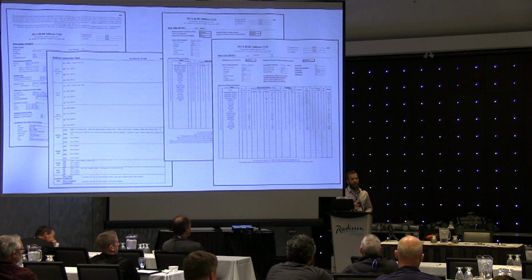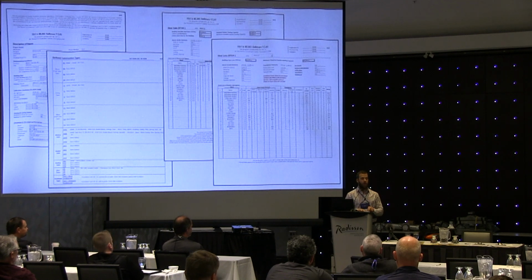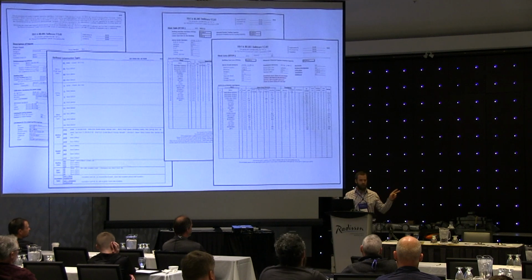Yes, in a way. All the building details, the location, what the walls and windows and everything are made out of, R values, you can confirm really quickly, like you said. However, the dimensions of each element, we don't duplicate on the results. So maybe I have an extra 0 on a window, and it's creating a ton of heat loss, heat gain. I might not be able to see that.